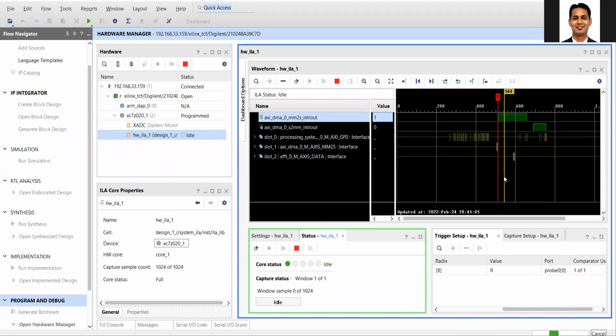Okay, and now here you can see the same code. Now you can see that nothing is happening between when the data is passed to the FFT and when data is received from the FFT, and that's where we get the speedup in the execution time, because you are saving the read from the status register. So this completes our lab on the improvement in FFT acceleration via use of the interrupt in the Zynq SoC.